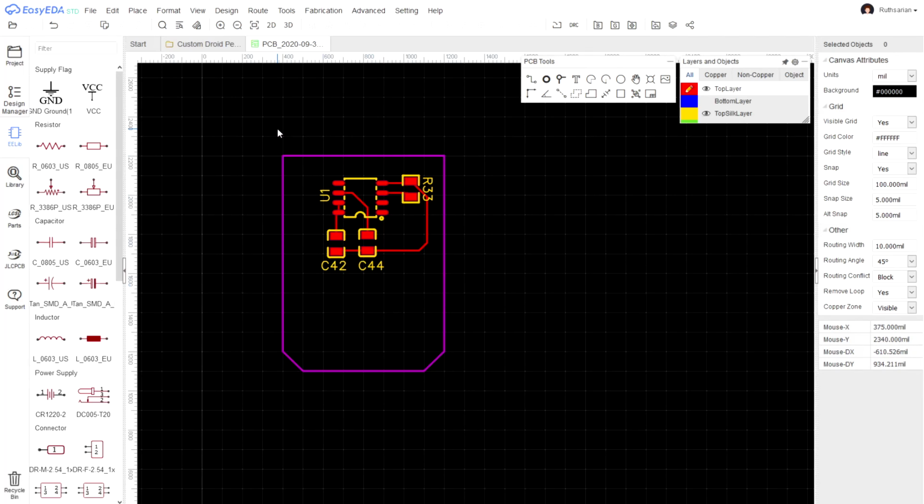We saw a 200 mil, and I think Winbond has a 209 mil footprint for their memory chip. So I'm going to make that footprint a little bit bigger so it could accommodate different sizes of those surface mount memory chips. And then I might also add a DIP 8 footprint so that you could use a through-hole memory chip.